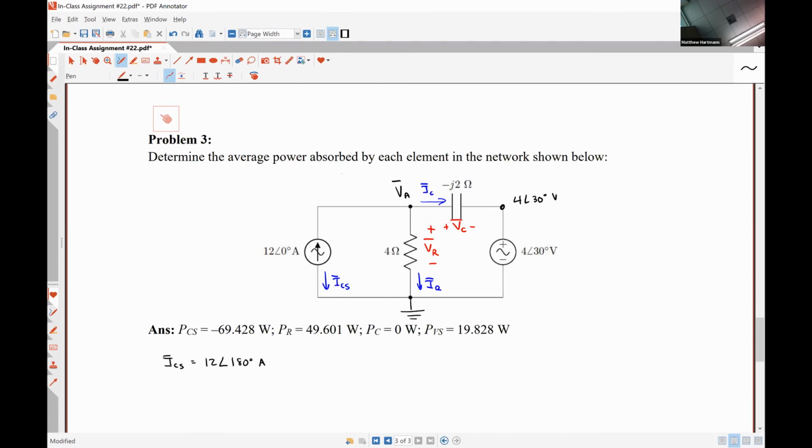My first instinct personally was to do superposition because then I could simply do current division and voltage division to get all the quantities I want, current division, voltage division, and Ohm's law. But I think your suggestion of nodal analysis, where we really only have one equation, one unknown, is shorter. So good eye.